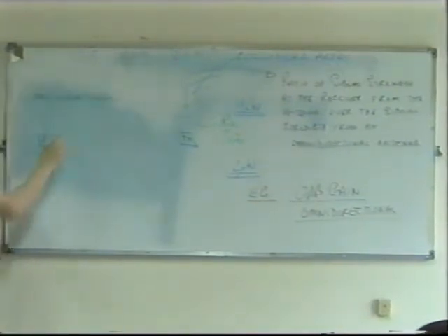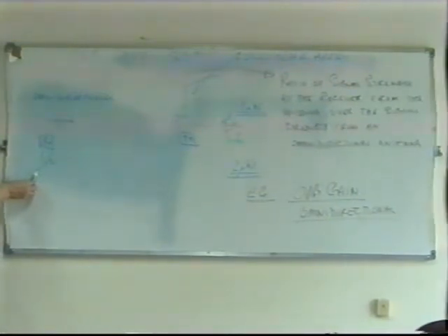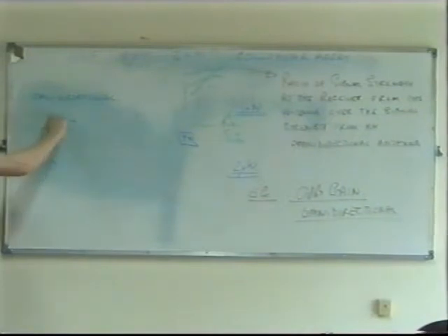Now I'm talking about the receiver now. What do you think would happen if, instead of using this dipole, I connected it to a Yagi? We would expect to get more than 1 microwatt in our receiver, because what I'm doing is concentrating my receiving energy in this direction.